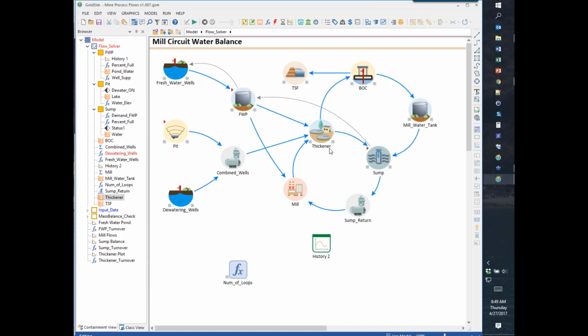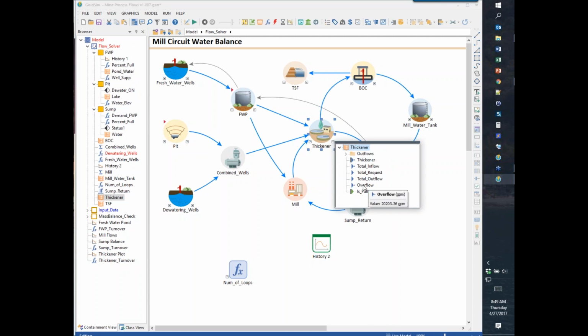That's a case you might have encountered if you're building these kinds of models, where as soon as you refer to the overflow, you'll see that you get a recursive loop error in your flow system, and that's because that output overflow is not a state variable like the pool element, or the pool amount, which is this output symbol that has a black line there.